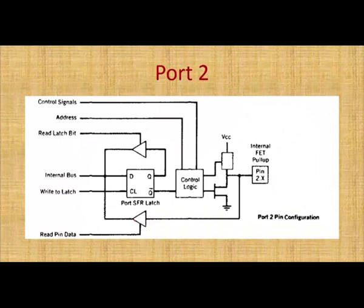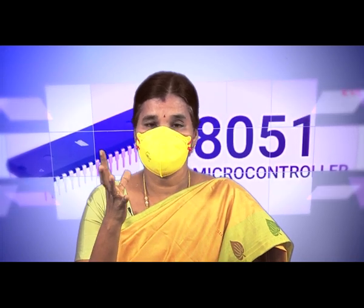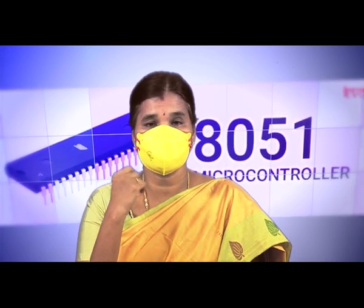Now, we will discuss port 2. Port 2 has 8 bidirectional signals, which are used as 8 input lines, 8 output lines, or 8 higher order address lines, A8 to A15. Now we will discuss how it is used as an input, how it is used as an output, and how it generates the higher order address lines.